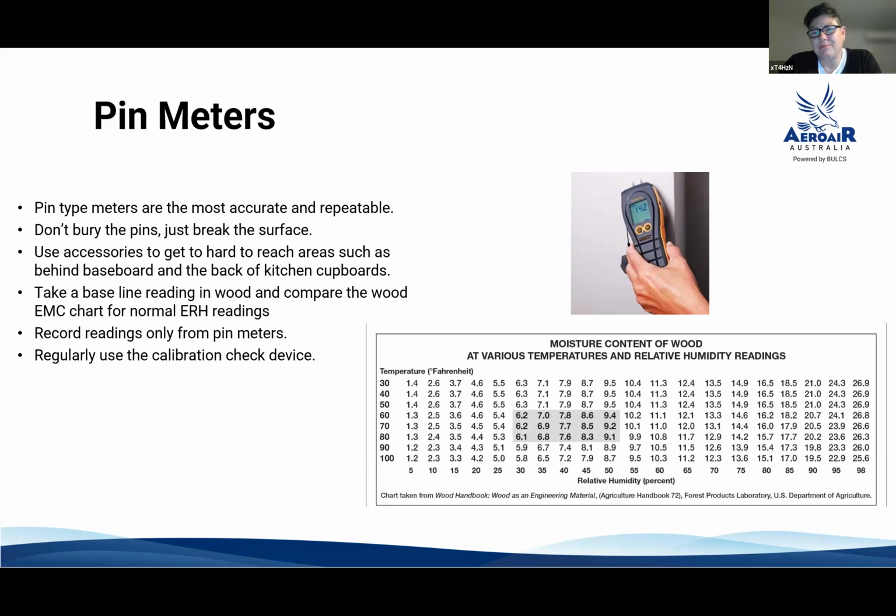However, there are meters that look at gravimetric readings, and the Protimeter uses its own scale. Protimeter comes from "protect timber", which is how the name came about. So it was built to look at wood materials, and its reading is from relative moisture content from wood moisture equivalent.